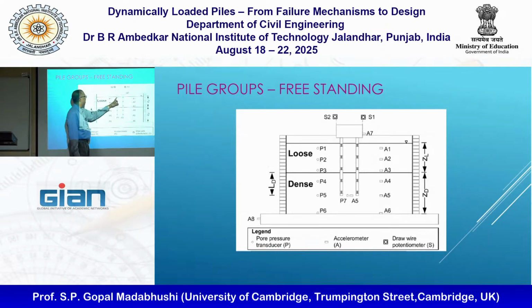So this is my ground level and I have a gap. Normally onshore, you don't do that kind of thing. The pile cap is either on the surface or even embedded into the ground surface. Offshore, many times you leave the pile cap a little bit free because you may not be able to drive the piles to the depth you want. So it is not totally made up. It is possible, especially offshore, to have a situation like this.